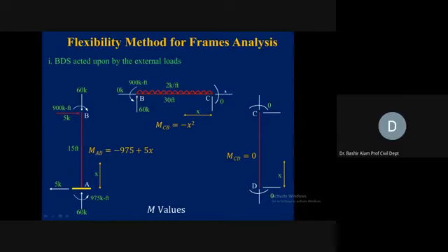Here I can give you the example of BC. If we take BC, this vertical is 0. So here the moment equation will be simply 2 times x squared divided by 2. But if we write from B to C, taking B as the origin, this will become 60 times x minus 900 minus 2 times x squared divided by 2. So it will have 3 components, whereas from C it has 1 component. So it is easier to take C as the origin instead of B.